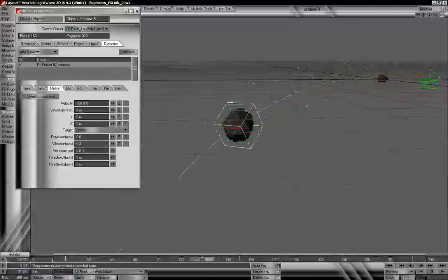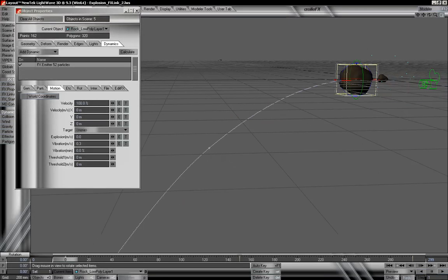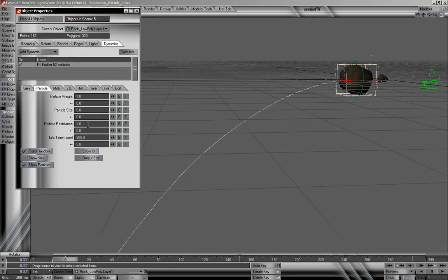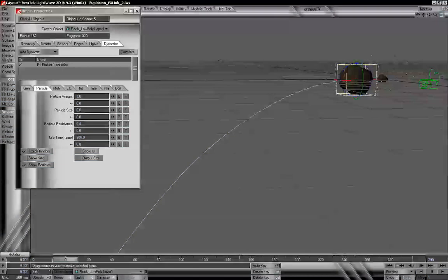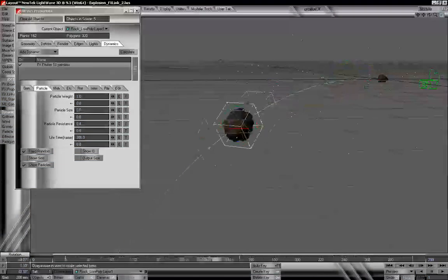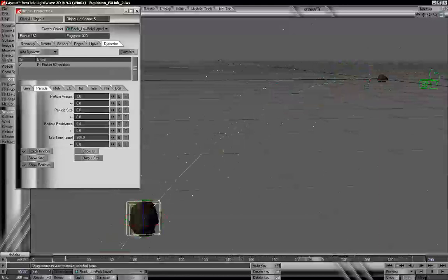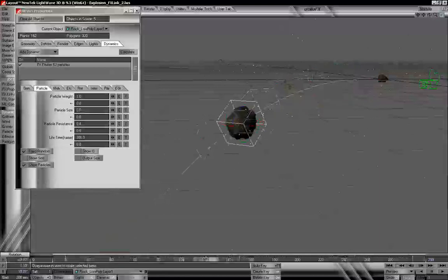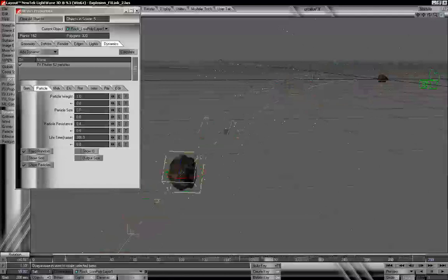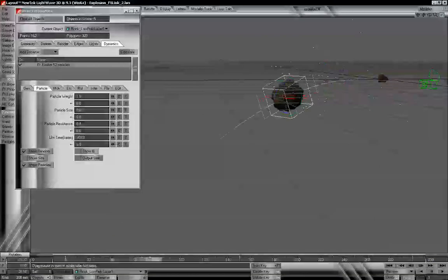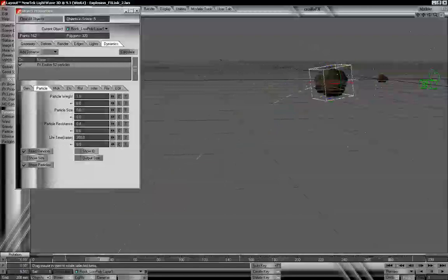So now we can see that trailing debris. I'm going to want to have a little bit of velocity with there and reduce the resistance. So I'm going to take our particle resistance, which is currently set to 1, and bring that down to 0.4. And we can take a look, because we do want these particles to continue and move out as the animation is going. We don't want them to stay exactly in the same place. We can also see how it is spreading out a lot further. But overall that looks pretty good.